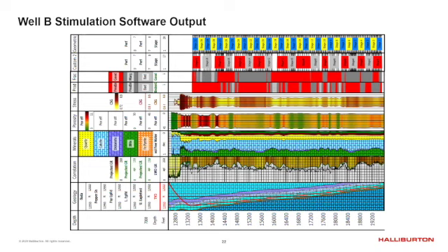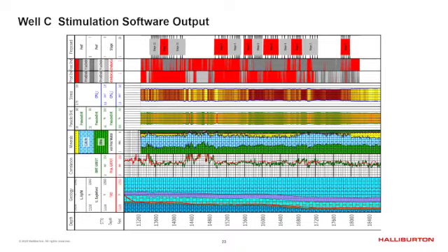So what that's telling us is that these rocks are failing differently than what we had predicted. They're failing in fracture mode. They're not failing in compaction. There's no compaction. That also tells us that there's a lot more stress interference than we probably initially thought, and a lot more near wellbore complexity, because we're altering the stresses in the near wellbore. So there's a lot of things at play here from the fracture mechanics perspective. There's a lot we don't know, but one thing we do know is that we can do a better job when the well is placed in the best rock. And I think that's what we showed here.